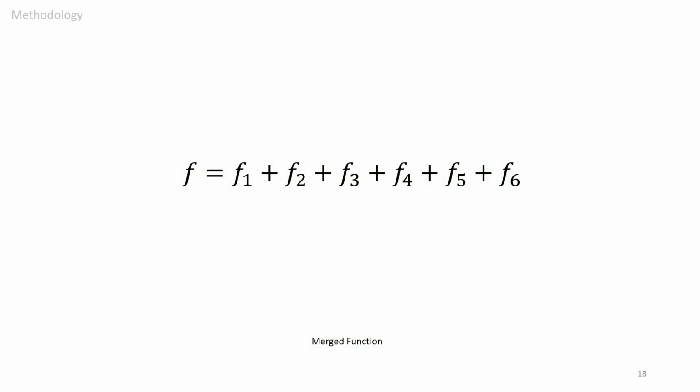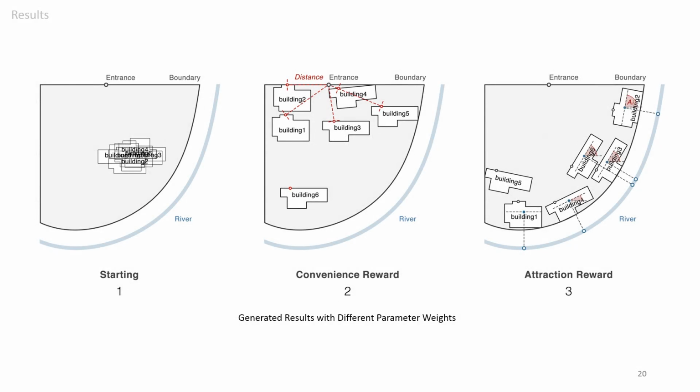Lastly, by adding all 6 functions together, the final objective function is completed. There are 6 coefficients, K1 to K6, adjusting the weights of subfunctions. Different settings of these six parameters may result in totally different optimals, showing the design choices from these different design requirements. First, K1 and K2 were always set as a very large number, so that once the geometric error happens, the penalty function will work in priority to drag the optimizing process back to the acceptable track.